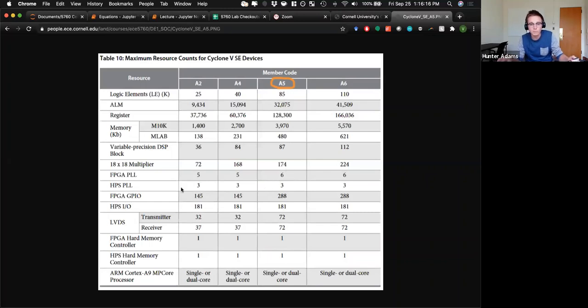Some other resources I can point out is the number of phase locked loops that are available. I mentioned that at a 50 megahertz rate, you have on the order of 1,000 cycles to play with between audio samples. I'll show you in a subsequent lecture how you can make your own PLL. So you could make a 100 megahertz clock, which gives you more effective cycles between samples.